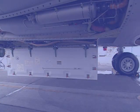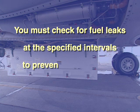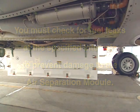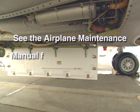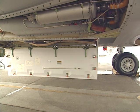Now let's take a look at the fuel leak check for the NEA distribution system. The air separation module can be damaged by fuel, so you must check for evidence of fuel leakage at the specified intervals. The example we'll see uses one of the drain valve configurations. The process is similar for airplanes with the drain cap near the backflow check valve. See the airplane maintenance manual for more information.